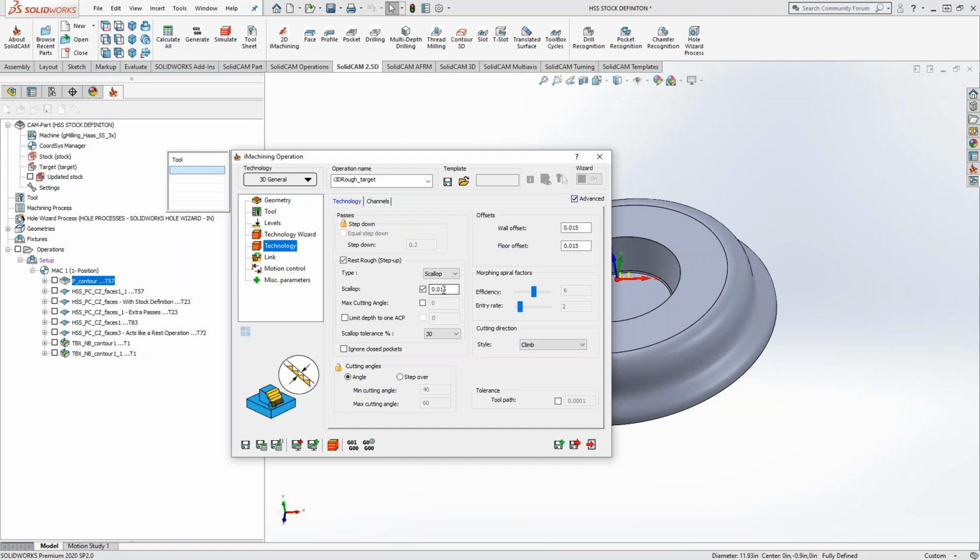So that's why it's nice. If you're not looking for the greatest finish out there, you can set the scallop at 5 thou, and when we're doing these molds, the finish was phenomenal. I was really blown away on how smooth it was in there. So there is that option there.